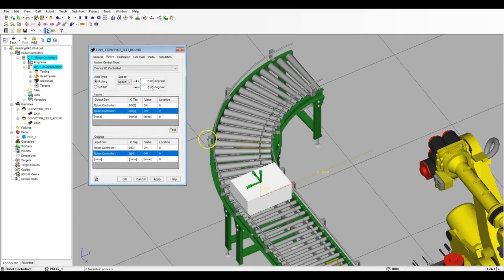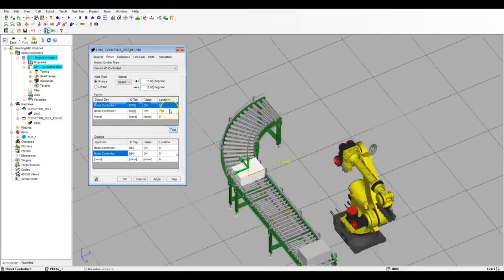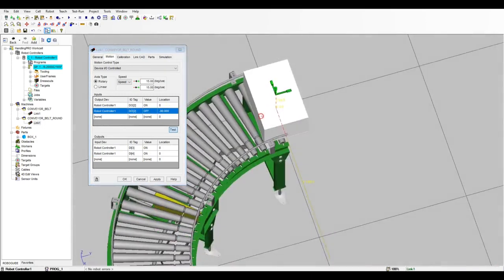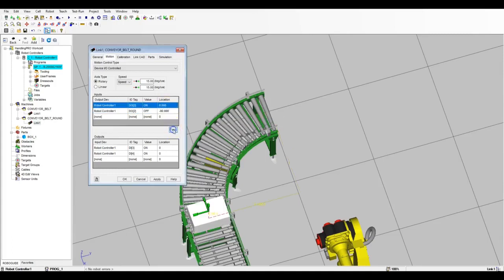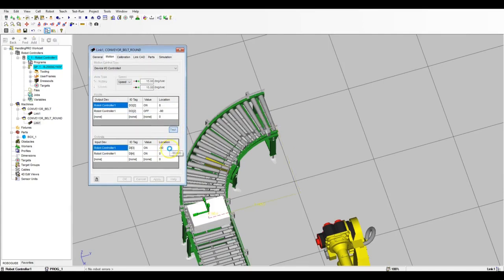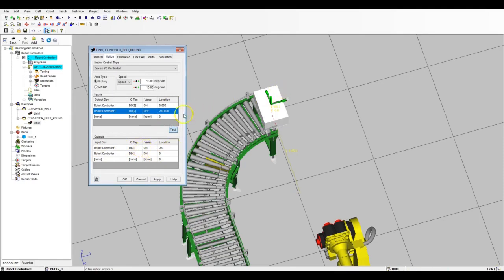So now we need to know the location. If we go location, so 0 is that, and then let's go -90. So no, -90 goes to the correct place as well. Okay, so we have 0, and then -90. So let's go in here. So digital 3, this one's going to be our -90 position, and then this is going to be our 0 position. So when we're up here, it's going to be digital control number 3. So when we're at there, digital output number 3 is going to be tested, and then this one is going to be digital output number 1.